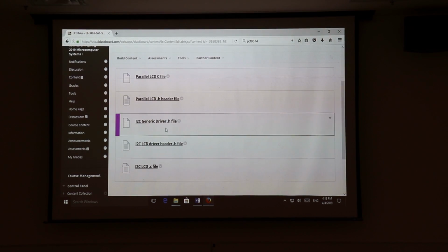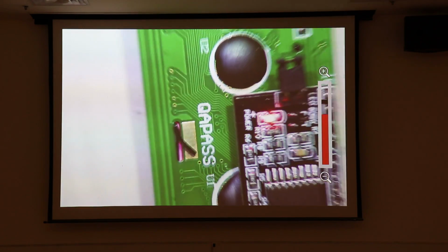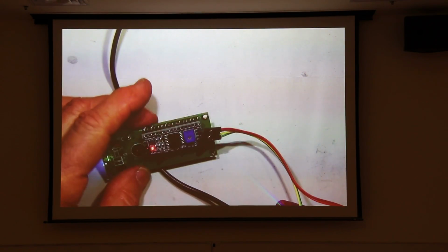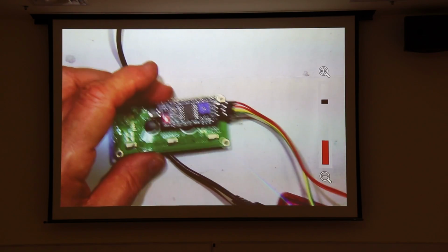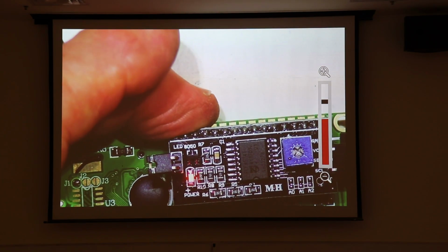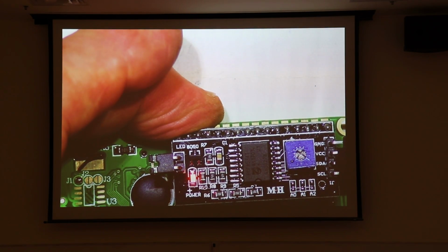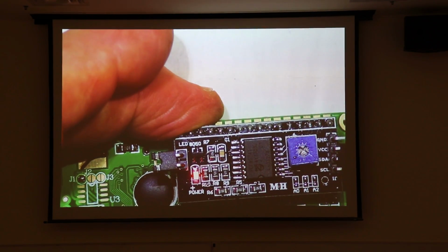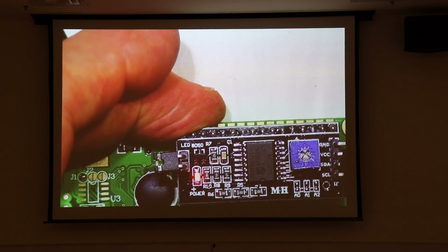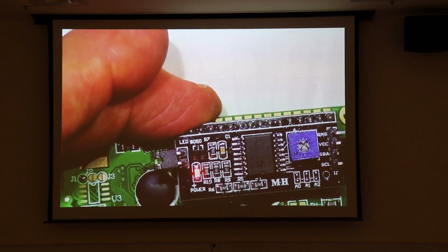And then that chip is connected to the LCD display, and I wanted to show you one more feature. So if you look at it, you see there's these 3 little areas here called A0, A1, A2. Those connect to the 3 pins on the PCF 8574. Yeah, 8574.